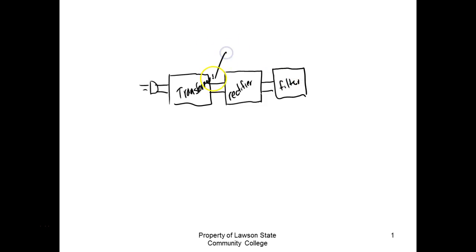Of course, what does the transformer do? Well, a power supply, it's going to step. You're right, but it's going to step. What'd you say? Don't say it changes the power. Don't change the power. It steps up the voltage. If it steps up the voltage, the current goes down for that wattage, right?